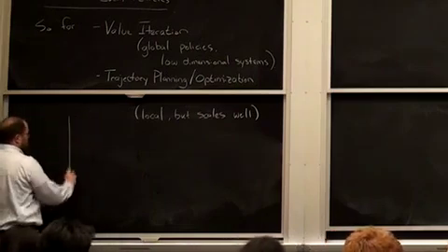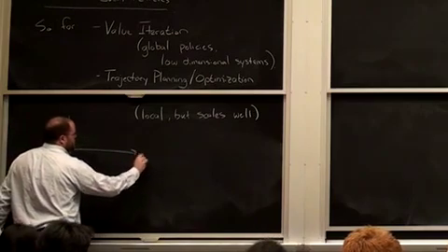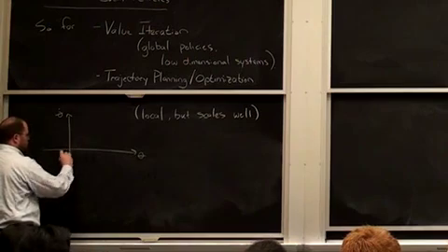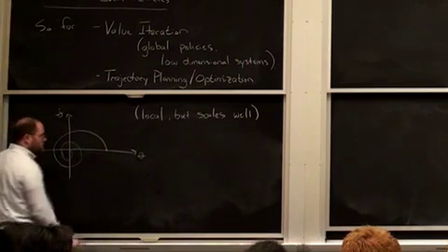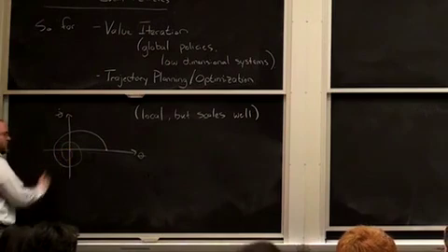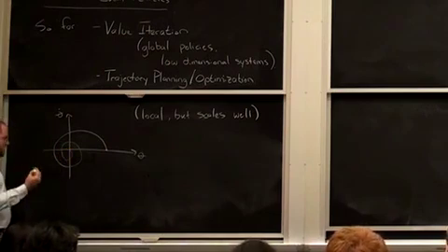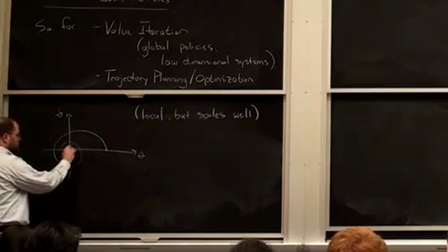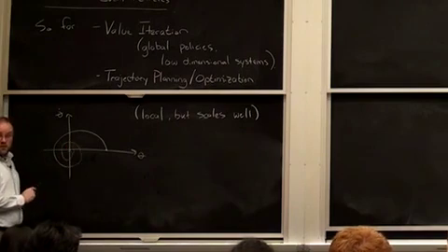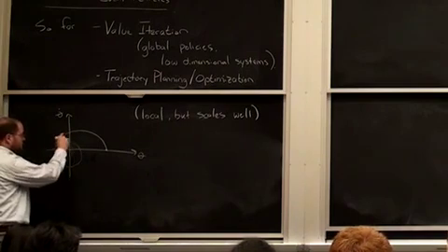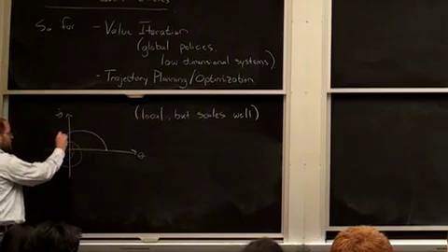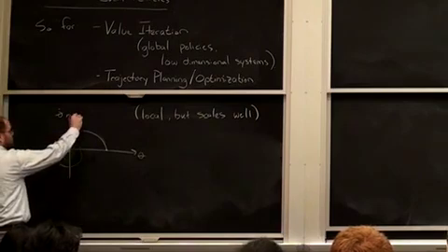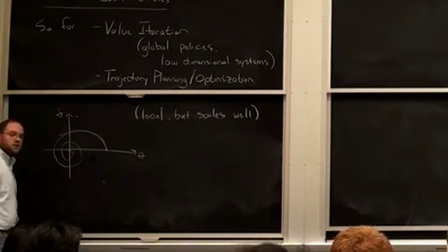Let's make our favorite picture. Let's say I've designed for the simple pendulum a nice trajectory which goes up and gets me to the goal, and that's good. If I start here, I know exactly what to do, right? We talked about stabilizing it with LTV LQR, right? So that means if I start here or here, I'm in pretty good shape. If I'm smart enough to index into the closest point on the trajectory, then maybe even starting here it's fine. I'll just execute the second half of that trajectory. But what happens if I start over here, or if I start over here, right?